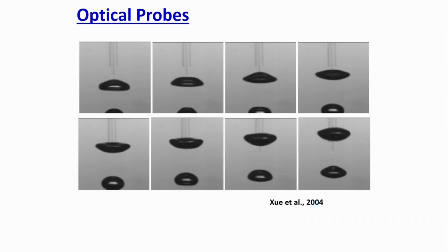What is good here is that because of the bubble piercing, you can also measure the size of the bubble, roughly. And if I measure the frequency of the bubble coming to the probe, I can also measure the volume fraction at that location. So, this is the major advantage of the technique. The bubble did not burst because of the precise technology and the very small size of the needle. So, the bubble actually passed through.